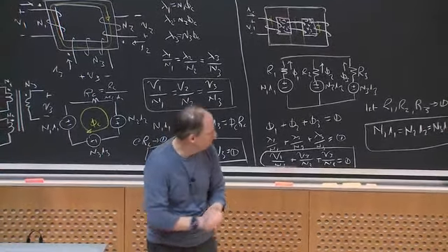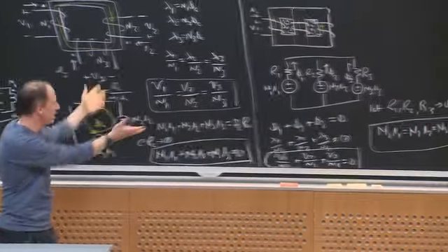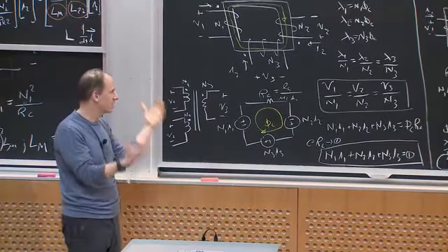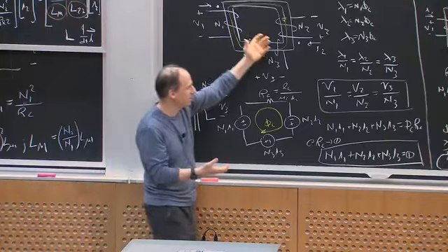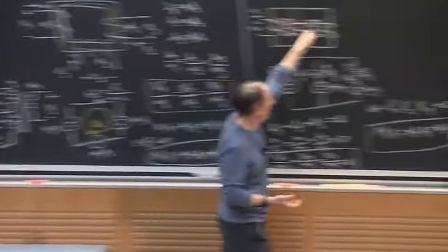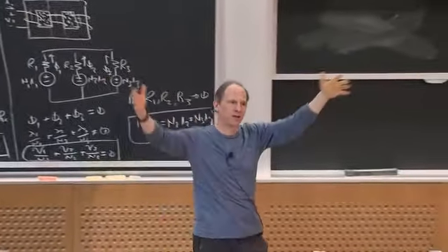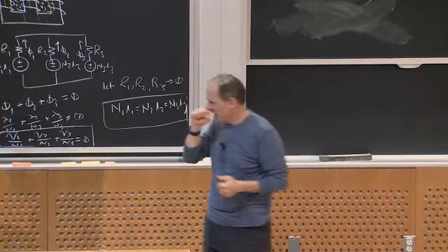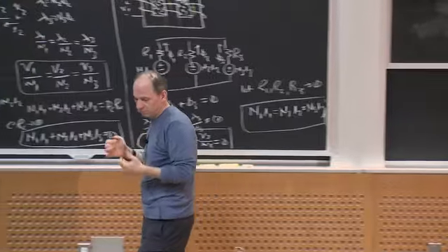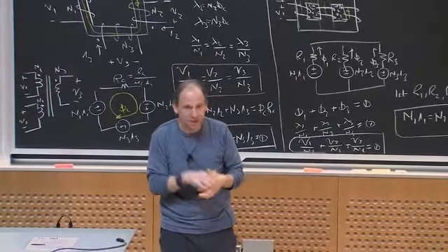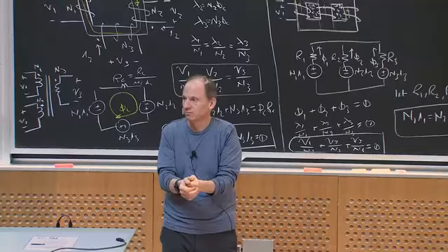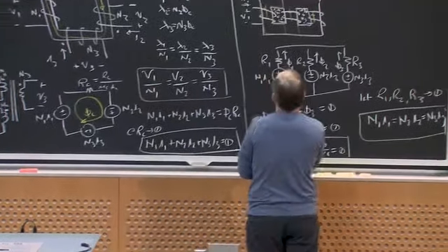Let's talk about the non-ideal. These are the equivalent of ideal transformer relationships for a 3-winding transformer. You could extend that for n windings. If I had n windings on one core or n parallel core sections, you just expand those relationships naturally. Okay? What would I get if I included parasitics? I would get a 3x3 inductance matrix, right? So what do I get in this case?